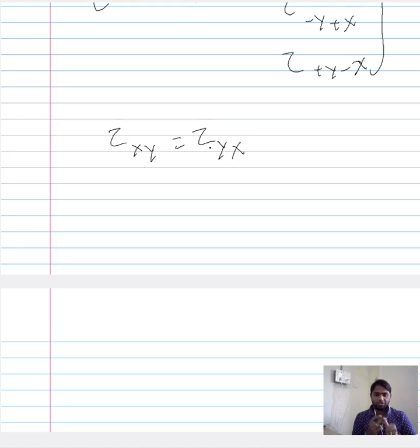For that, we need theta and phi. This theta and phi depends on the plane that you have considered and the direction that you want to go. But so far what we just want to focus on is just how many components we need. That is all our focus. So we have seen that when you consider a three-dimensional setup experiencing a triaxial loading, we need three components of stresses.